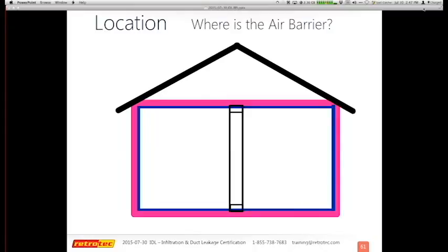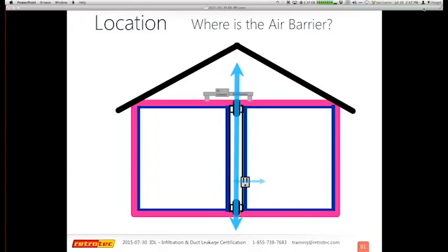So it's easy to do when you just have one room. But when you start chopping things up and adding multiple rooms, now my air barrier, which is typically the drywall, has been cut or separated. Now I'm getting connections to the attic or crawl space. We put some receptacles in or plumbing or other stuff. And now, as you're all familiar with, we get major connections to the attic or crawl space, a lot of air moving through interior or exterior walls.